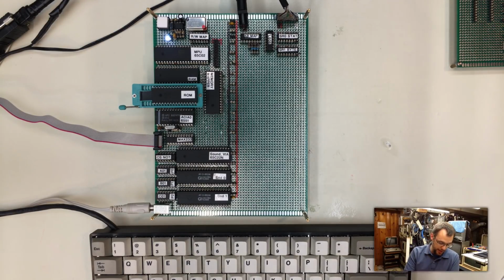And then when you would hit enter on the keyboard, the monitor interpreter would see all these zeros, get confused, and say, well, you're trying to type an S command, but the command is invalidly formatted. Error, and it would throw an error on the screen. It wouldn't execute commands correctly. If I tried to list memory anywhere other than at the 0 location, it would try to list memory at 0, because it was as if you were typing L by itself. It wouldn't receive an address value and things like that.